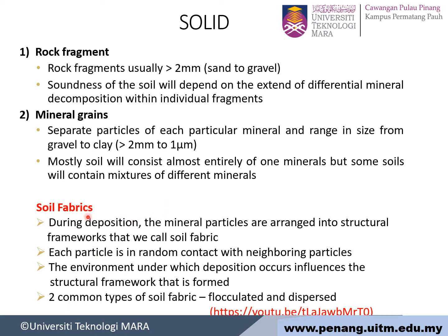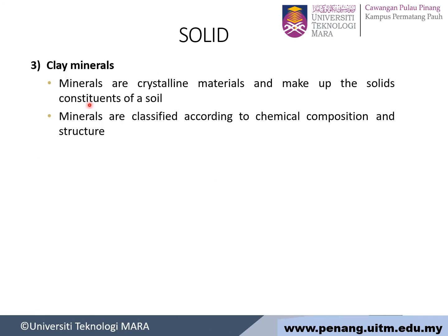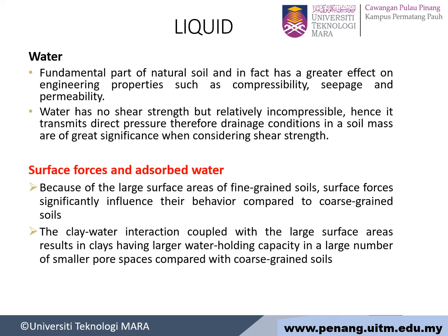Soil fabric: during deposition, the mineral particles are arranged into structural frameworks that we call soil fabric. Each particle is in random contact with neighboring particles. Two common types of soil fabric are flocculated and dispersed. You may also refer to this YouTube website. Another solid is clay minerals. Minerals are crystalline materials and make up the solid constituent of soil. Minerals can be classified according to chemical composition and structure.